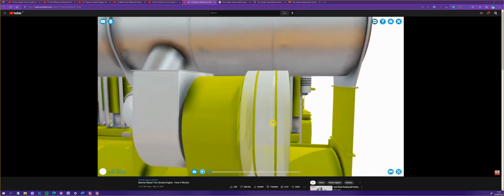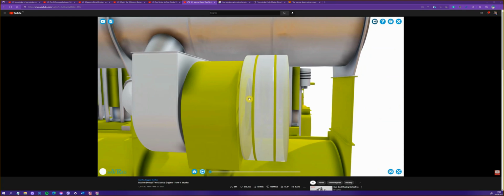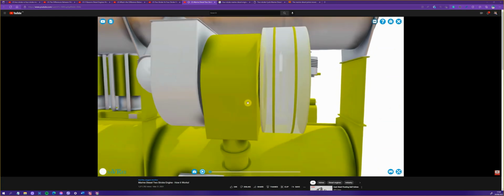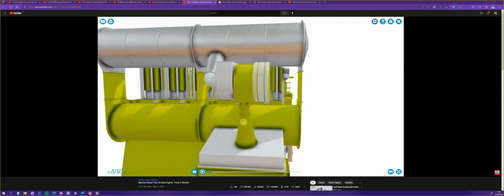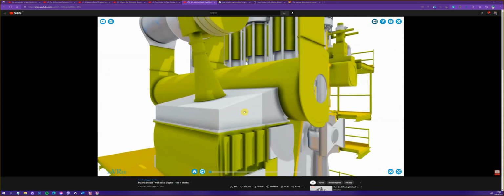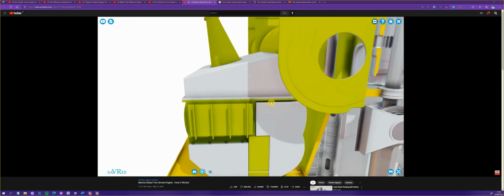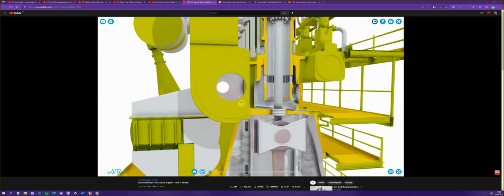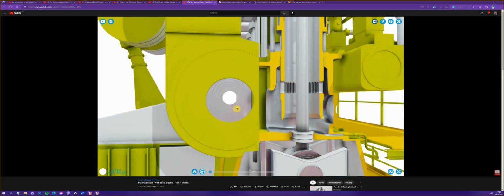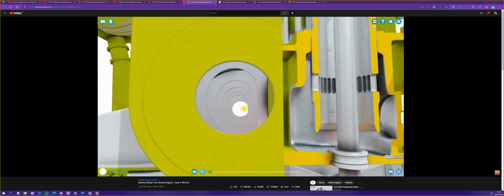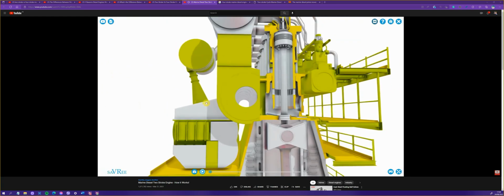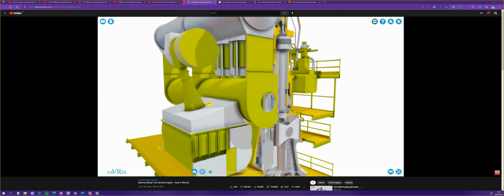Air actually gets sucked in through these filters here in the turbocharger, and then we pass that compressed air into a cooler. This would be our air cooler, and then the air cooler discharges the air into our air manifold, what we call our charge air manifold. That would be this space inside here. How much air do we need? A lot. Not just depending upon how fast the engine is going, but generally just quite a lot.